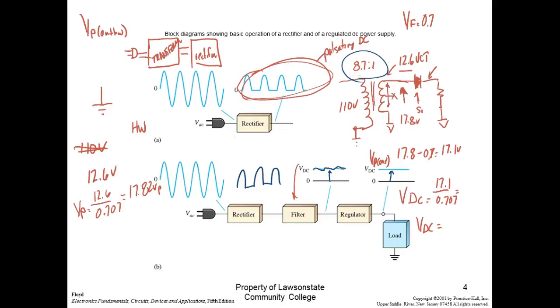And then the transformer has resistance. In one class we used to teach on transformers, they actually calculated the resistance. So what you do is you short out the secondary, and you have what we call a variac on the input. A variac is a device that you can use to put in a variable AC voltage. And then they'd crank it up and measure the current, and then they could calculate the resistance of the transformer, the actual true resistance of the transformer. So transformers drop voltage. It's just that simple.